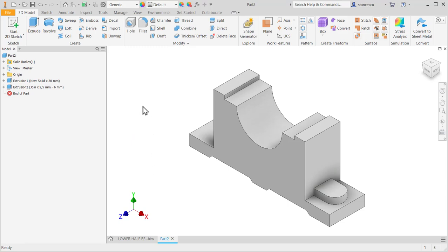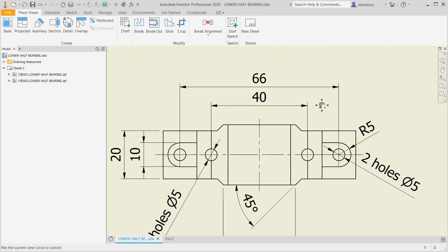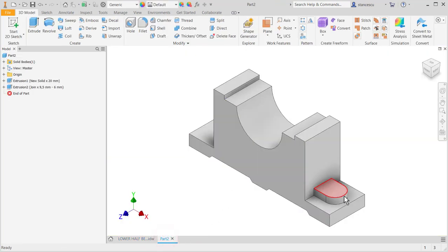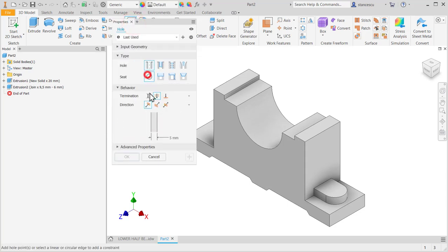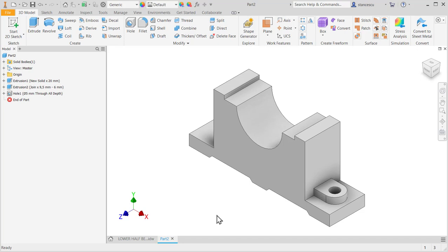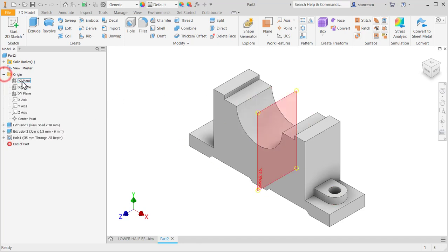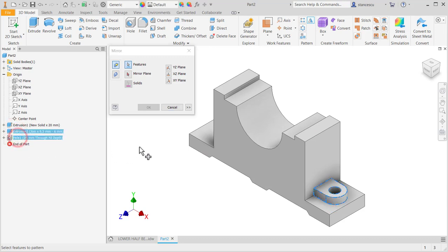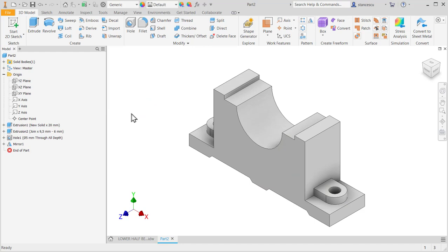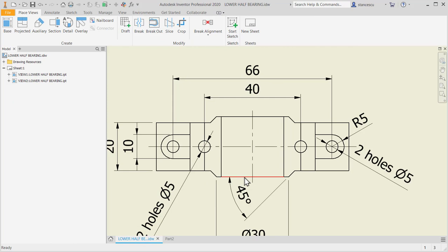Okay, now there is a hole of 5 centered here, simply a hole of 5 on this face, concentric with the exterior. Okay, I mirror this because everything is centered in the system of work planes. Then I select mirror the last two features about this plane. You see here what this should be. Okay, now I create this.